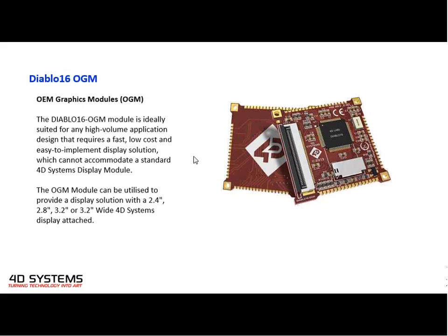This is attachable to the main board, to your application board. It's like an assembly module, so it's soldered via the connections here. It already has a header for the flex connector, and it can interface directly with the 2.4, 2.8, 2.2, and 3.2 inch wide-aspect displays that we also sell separately.